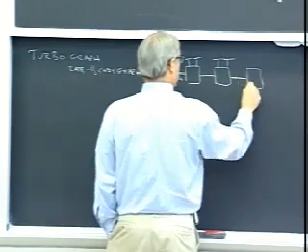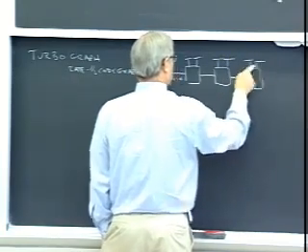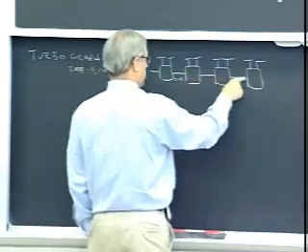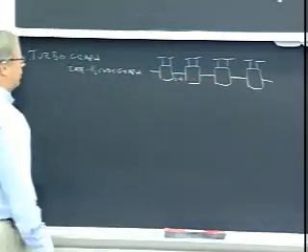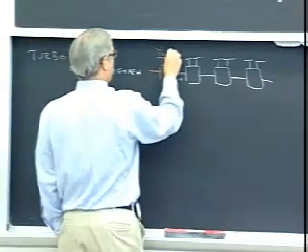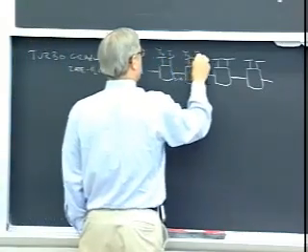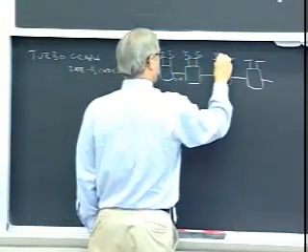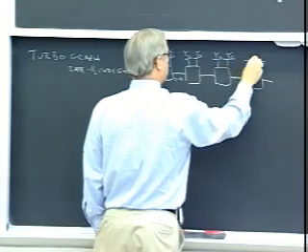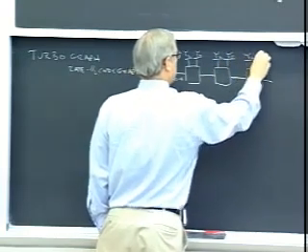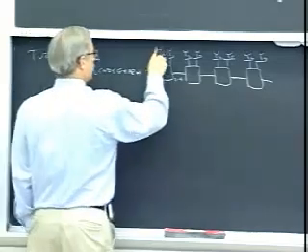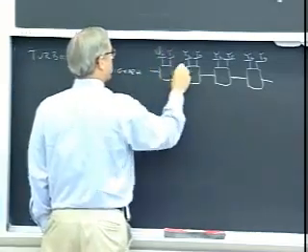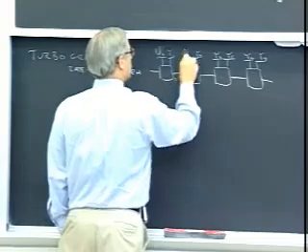So this is what it looks like. We get one of these for each unit of time. This is the branch constraint for each unit of time. This would be Y0, Y1, Y2, Y3. You get 2 bits out per each unit of time. And in this case, one of these is actually the input at that time, U0, U2.